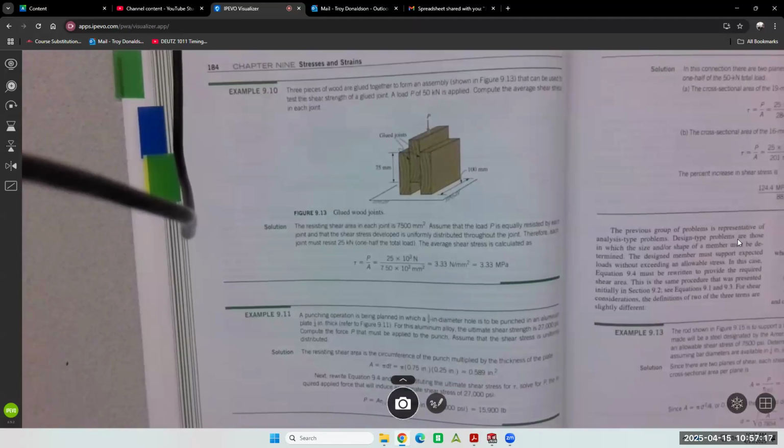In a glue joint, is it the glue breaking? Absolutely. That's exactly what I was leading you to. When you calculate that shear stress of a glued joint, you compare it to the properties of the glue that was used. So when we're laying up a roof and laying that plywood on the roof and gluing it down, you can't just go by Gorilla Glue. What's the properties of that? Who knows, right? You have to use liquid nails rated at whatever. So that's what you would compare it to. If you're using epoxy, then there's always ratings on epoxy. So that's what you compare it to.